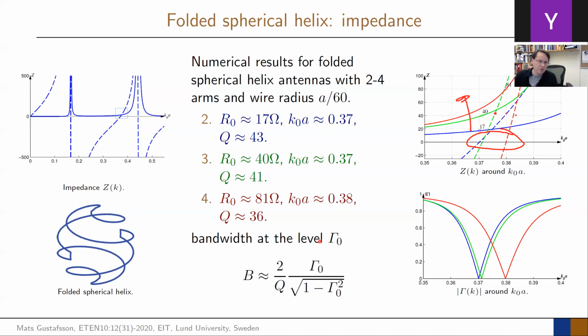So that is one of those tricks that can be used when we shrink the size of an antenna. Folding is really a basic, simple one that you've learned in this course, and it works for many types of antennas, not for all. And then you have to do other tricks in some ways to push it down. But it can be done in some ways.